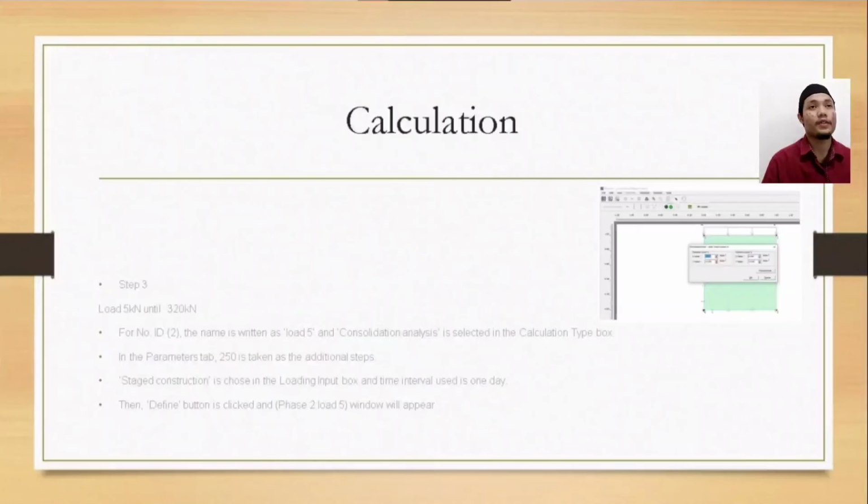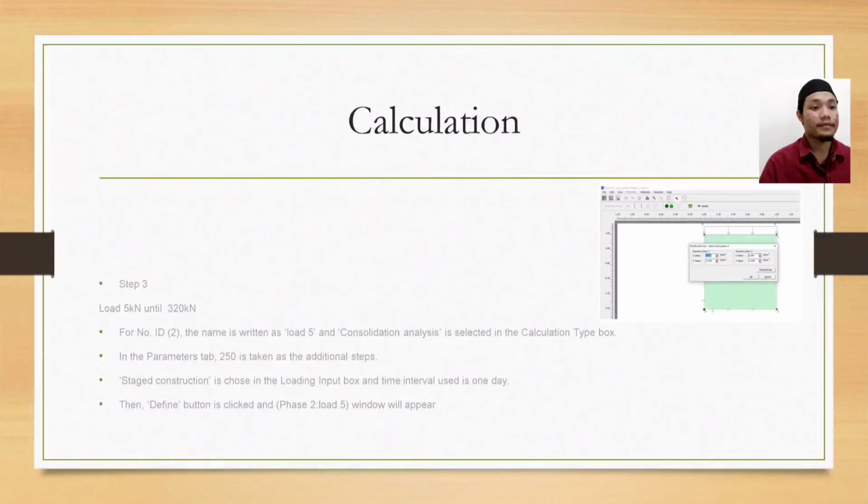After the starting sample is done, we can continue to the consolidation process. For the consolidation test, it is the same step, but we must change the last step. We must put in the duration of the sample. For example, in this situation, the sample will take 1 day to run. We will apply and run all at the same time.